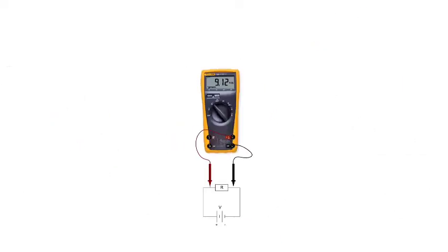See, if you do not want to insert the probes of the multimeter onto the breadboard, what you can do is you can also measure the voltage by simply touching the probes of the multimeter on each end of the resistor as shown in this figure. All right, which is a simpler way of measuring the voltage.